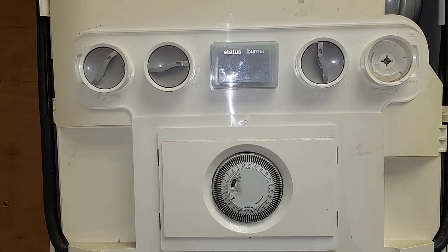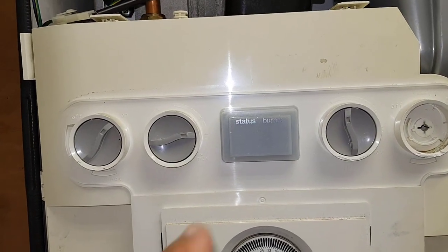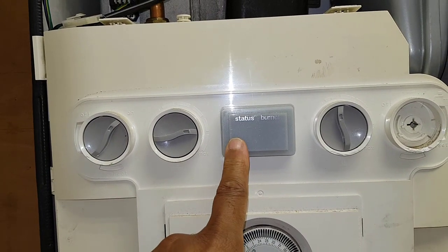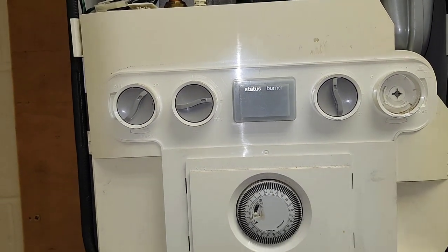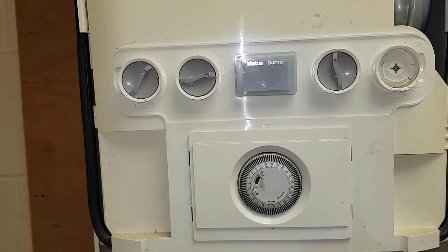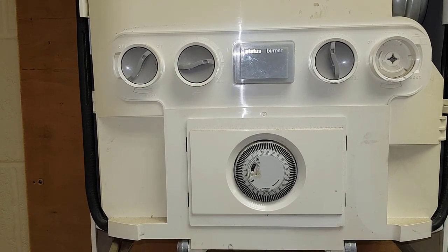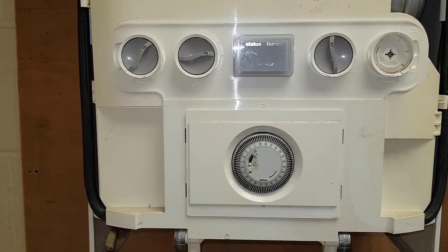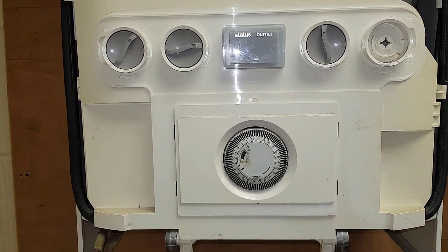We linked the room thermostat together and it didn't come on the C. Then we look on our fault analysis quadrant and it says on there PCB. So that gives us a guide where to look next. That's correct. So you can see the framework of this. It's helping people like yourself get a bit more familiar and something to work to. It gives you guidance of where to look next.